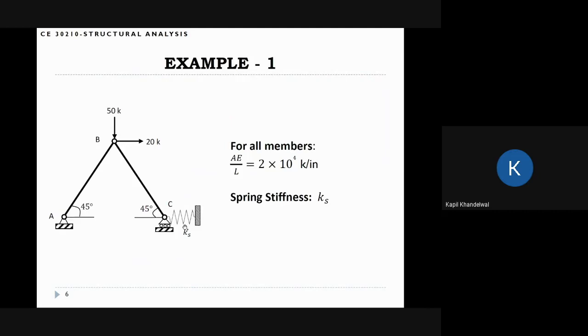And if you think a little bit carefully, you can see that there is a problem with this kind of structure, because this roller can move, and there is nothing to resist this movement. So it seems like this is a physically unstable structure, and we want to see what is the mathematical quantity that reflects this kind of instability. As we already discussed in the previous slides, that mathematical concept is eigenvalues. Eigenvalue is a very important concept, and we'll see that this concept of instability will be reflected in the eigenvalues of KFF.